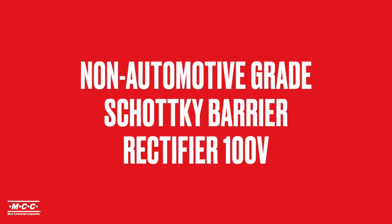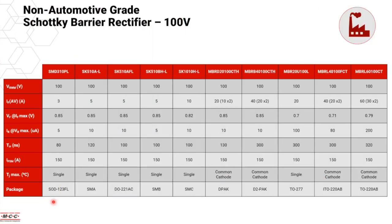This page shows you some examples of the industrial grades or the non-automotive grades of Schottky barrier rectifiers in the 100 watt range. These are all 100-watt devices, and the rectified currents offered are from 3 amperes all the way up to 60 amperes. It comes in single channel configurations or dual channel configurations. This is the dual channel configuration.